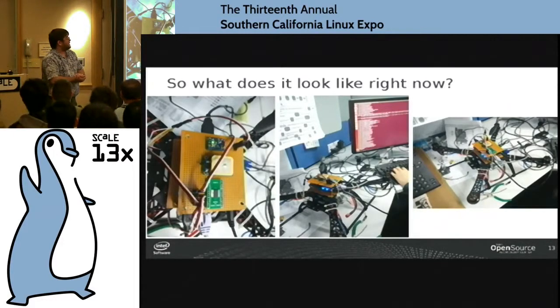And the other nice thing is that we provide libraries and footprint, basic boards to allow you to create your own add-on boards. So that 10th-inch header on the top, we've got boards that click into place and have the same mounting hole, so it's really easy to stack things. The header on the bottom is a 60-pin high-speed header, where we've got PCI Express and those kinds of things. If you want to do differential paired signaling, which I hear KiCad can do now, as of, I think, 3 days ago.